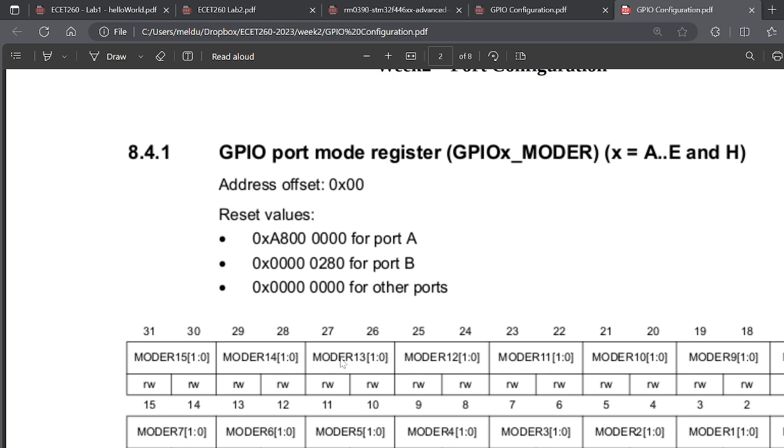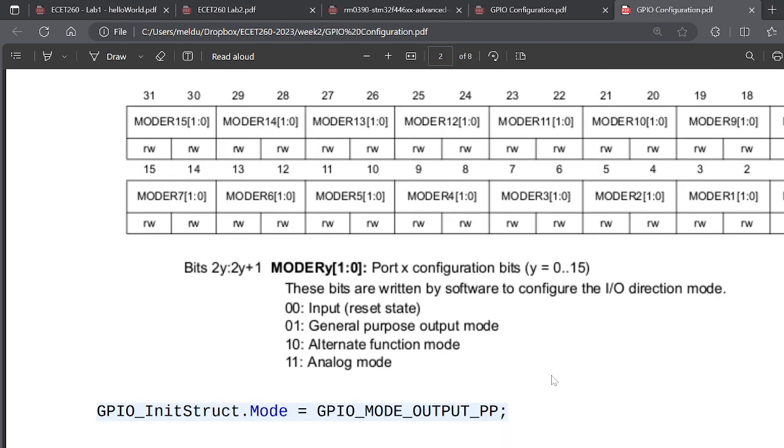If you try to write to an extra register, does it erase or overwrite the first one, or does it return an error? Yeah. If we look at some of the code, there are checks to see if you have put things that are out of bounds in most cases, and it will say, I don't know what pin 32 is because it goes from 0 to 31. But it won't wrap around or do anything like that. If anything, it will truncate and you just get whatever you had there. A lot of the code has these directives in the functions to say, did you ask for 16 bits on a port? Did you ask for just 32 bits? So it is pretty good at some of that.